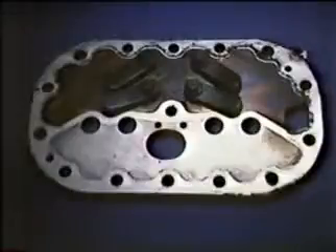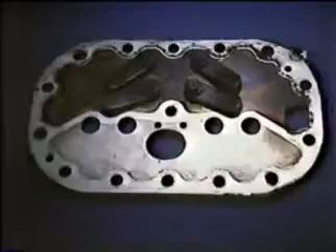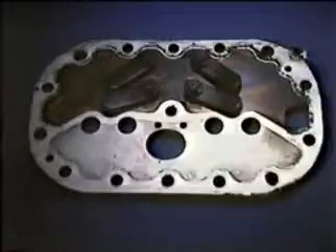throughout the entire system. The most visible clue of severe overheating in a compressor is carbonized oil on the discharge reeds and the discharge side of the valve plate. This valve plate has been discolored due to oil breakdown. The same tremendous heating effect that caused this carbonization also weakens discharge reeds so that they leak or break. Another clue shows up as fine iron particles in the oil.